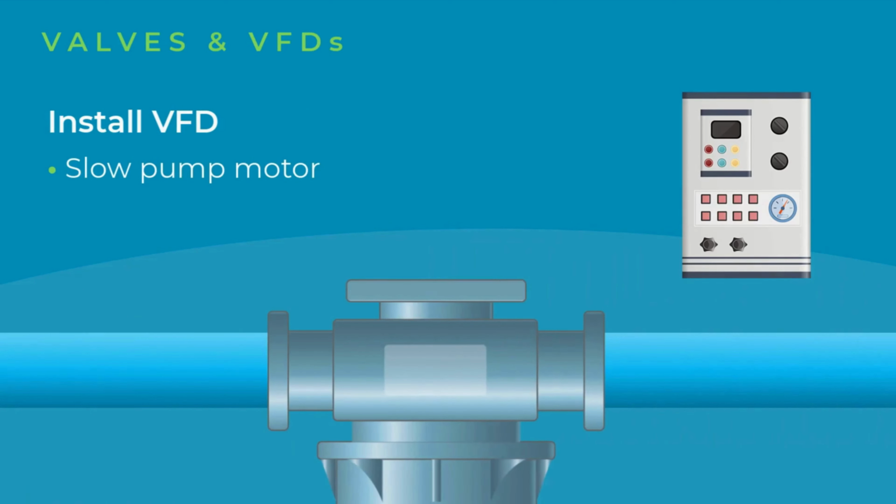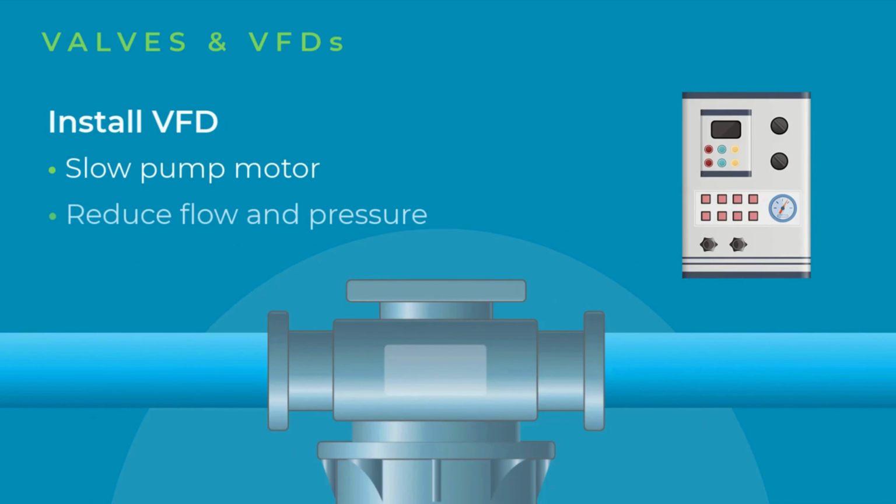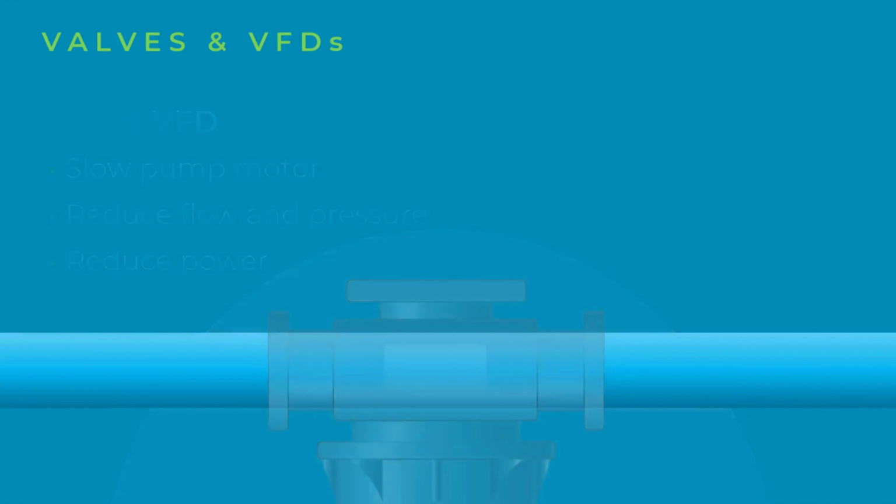When a pump operates at a slower speed, the whole pump curve shrinks, meaning the pump does not produce as much flow or pressure, and the power requirement to operate a pump can often drop substantially, since pressure varies exponentially with a change in flow.